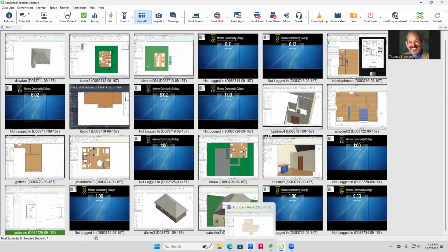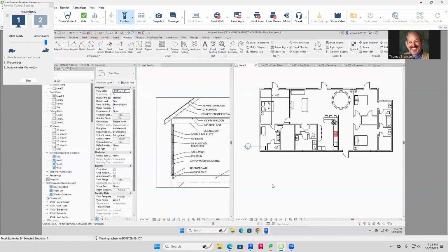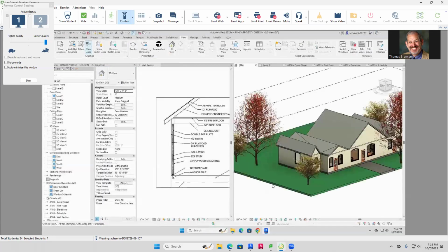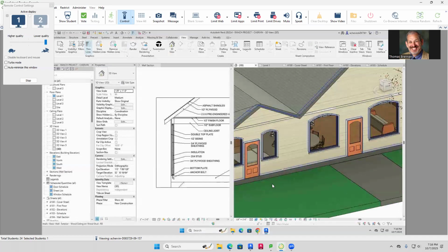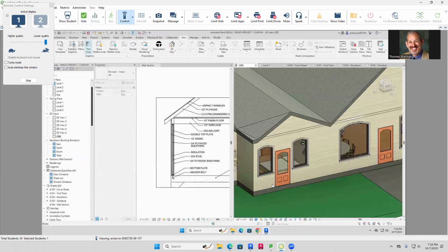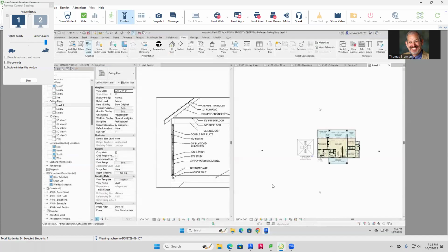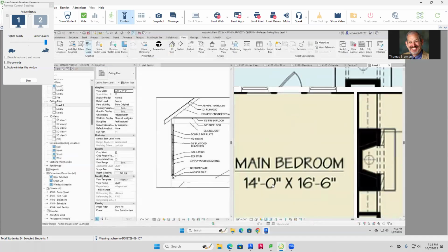And another question. Is it okay if I have the visible line between the roof and the ceiling? You can see the ceiling. Okay, what you'd want to do is go to your ceiling plan and take the ceiling, go to the boundary, and just pull it inside of the face of the wall. Follow me? And if you need to hide that image, that would probably help.